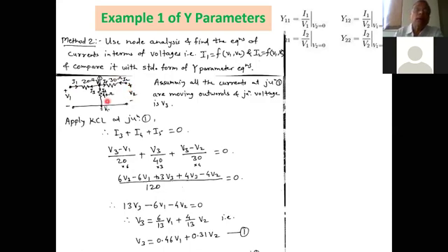So except for V1, V2 and I1, I2, we now have to assume the voltages and currents in the network. Keep this in mind. Otherwise, you may write V1 here as the voltage of the first non-reference junction, and at the end you may get confused between this V1 and the V1 voltage at port 1.